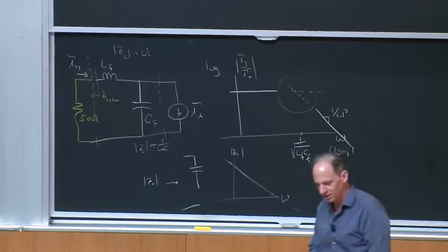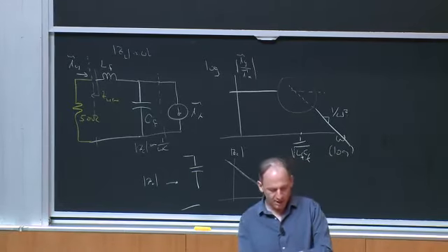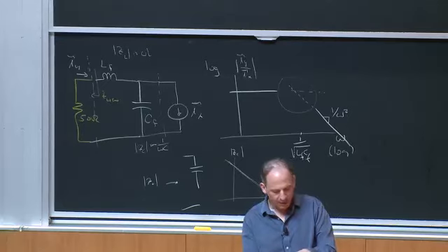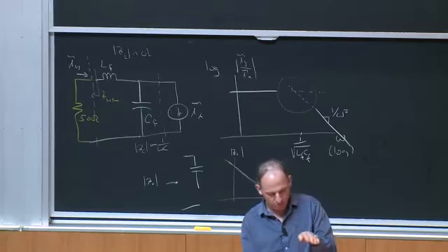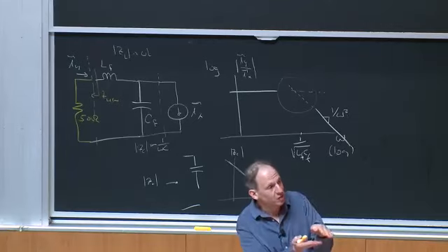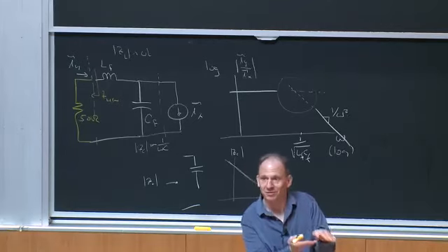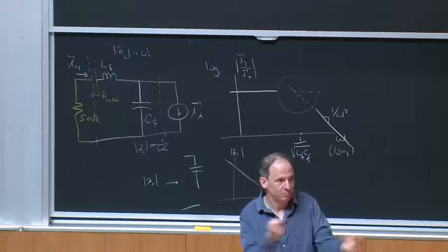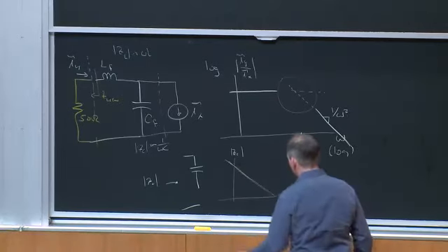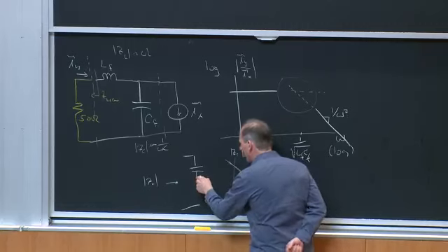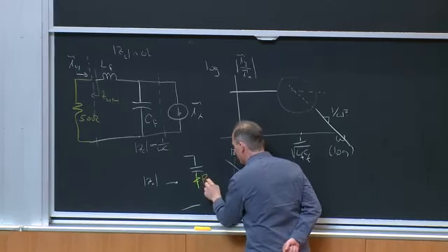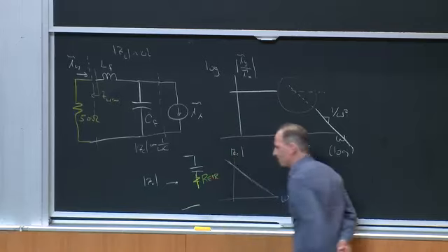Well, a real capacitor, even though I think of it as an energy storage element, the plates do have some resistance. There's actually some resistance of the wiring going into that thing. So as a practical matter, a real capacitor is going to have some ESR, equivalent series resistance.